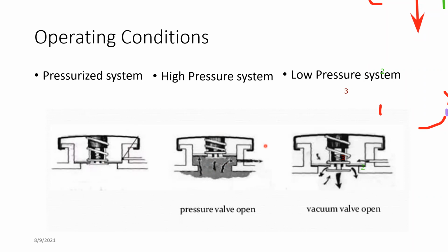That's around 15 psi. As I told you earlier, it should be around 15 psi. Until it comes to around 16 psi, this valve will keep it open. And once it comes to 16 psi, it closes again, and temperature is maintained, the engine operation is maintained, the engine has no issues, right? Since the temperature increases, this valve opens, the liquid coolant goes out, and the engine is running fine. That's what usually happens.